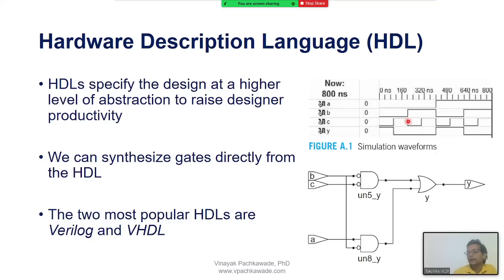Once this verification through the waveform analysis is done and the code is verified, another tool called a logic synthesis tool will be used to take that hardware description language code into account and directly generate a circuit, or logic, out of that. The tool will decide which logic gates, which unit cells to take, and accordingly directly synthesize or create the gates or circuit from the HDL.